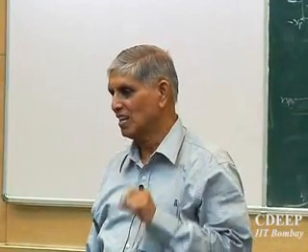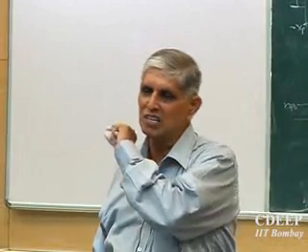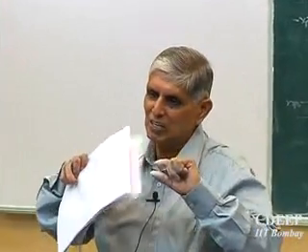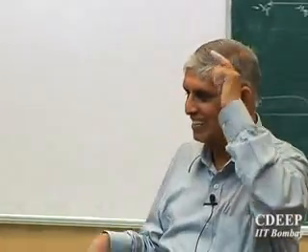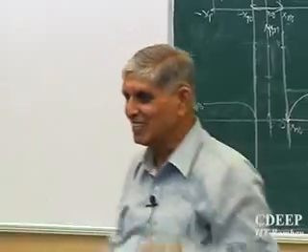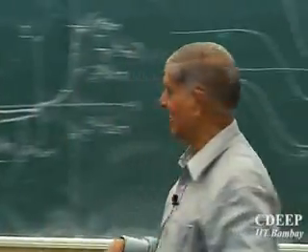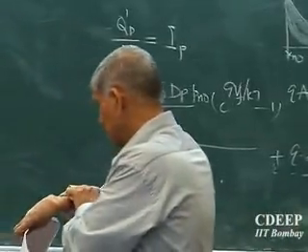Is that point clear? This fact is very crucial in all designs, that there is an electric field in the neutral region which is very small but necessary for carriers to be brought to the contact. But as far as its value is concerned, we can still treat it as very small, tending to 0, and then solve everything together. Is that clear? These two facts are not correct, but you should mentally adjust that this is how it is treated, though it is not actually so. Okay, time is up.